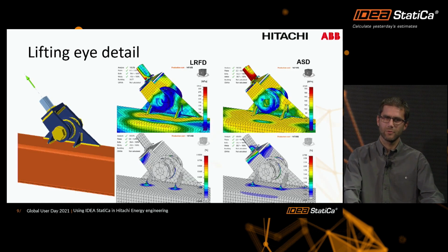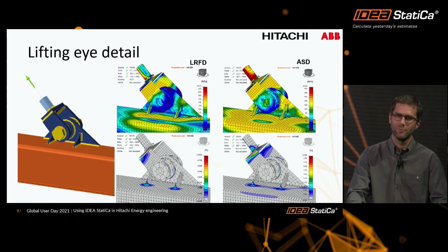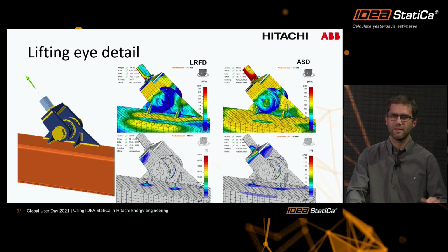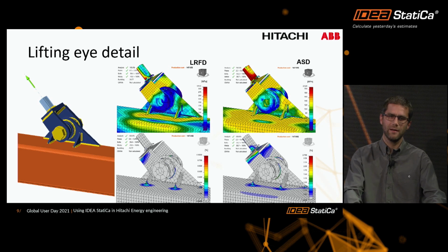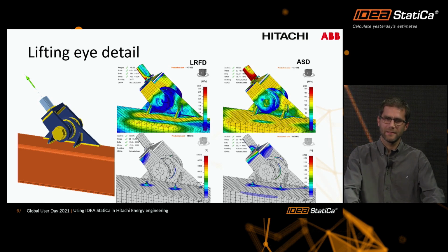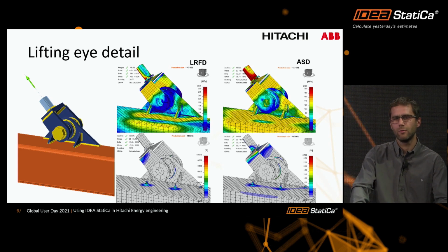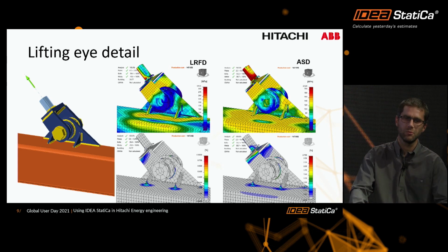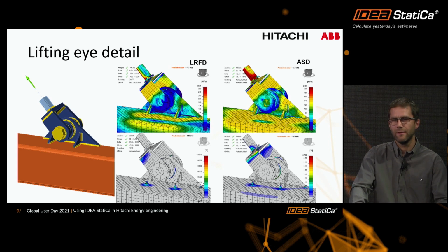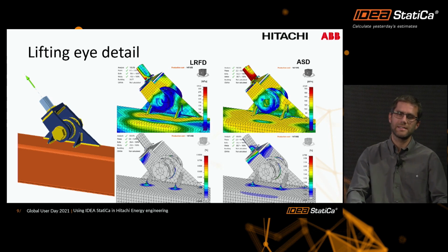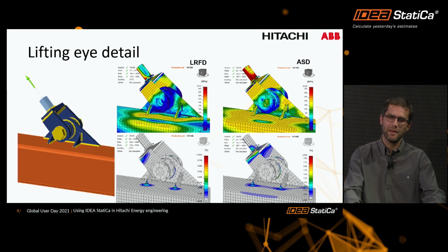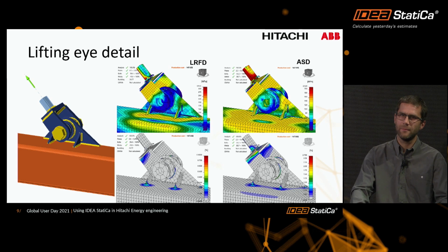So that's why it was time for IDEA StatiCa to model it or transfer it from Tekla Structures to the model in IDEA StatiCa. Actually, at this time, it was not clarified what type of analysis we were supposed to use. For sure, for us, it would be easier or better regarding the total weight and regarding the stresses to use load resistance factor design. But as we were not sure, we provided both analyses. Anyway, both of them